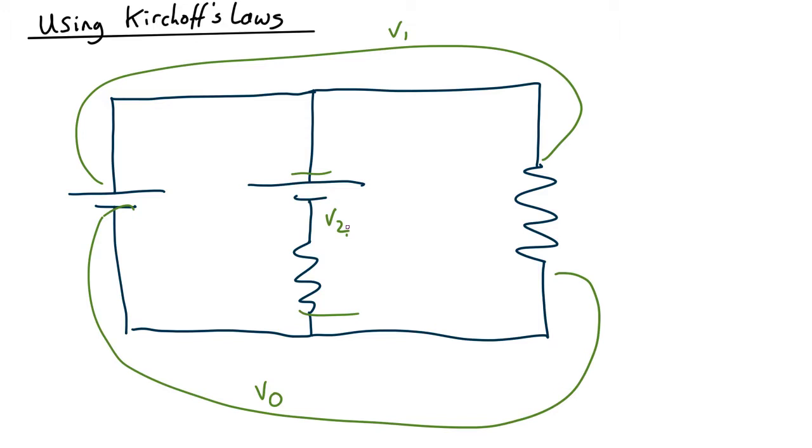Now draw currents. Now you may not always know which direction the current is going to flow. If you don't know, just guess, and if you got it wrong, you just come out with a minus sign. In this case, for example, depending on the relative voltage of these two, the current could go either way through here. Anyway, let's call this one I1. And we'll call this I2. I'm guessing it goes upwards. And we'll call this, now you can either call that I3 and then solve for it later.